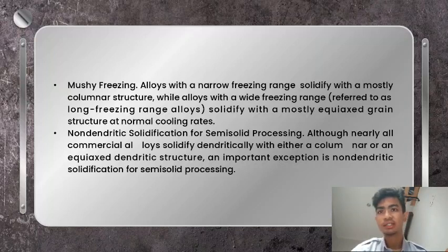This local enrichment suppresses growth of the first crystal, but creates conditions favorable for the nucleation of the second set of crystals just beyond the first set. The process is repeated as many times as necessary. The grain starts to tend to equiaxed if crystal growth is sufficiently suppressed. The dendritic growth also can be suppressed.